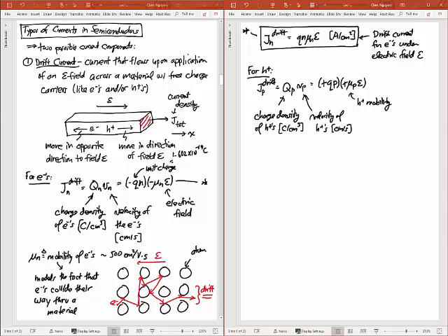which is about equal to 250 centimeters squared per volt second. You can see that's about half the mobility that electrons had, for reasons that I just described. And so finally, this whole thing I can write as Q times P times mu P times E, and that then equals the drift current density of holes. So I pretty much just derived the same equation for holes there.